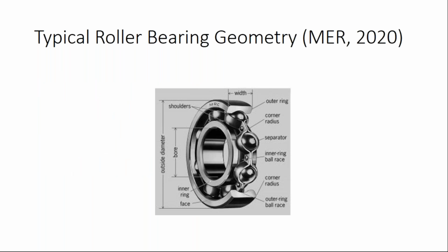I've just got an example of a ball bearing, and as we go on, we look at the bearing defect frequencies. So one should remember that bearing defect frequencies occur, and they're not always above the allowable limit. If you look at your vibration standards, you can usually judge whether your machine has bearing defects or not.